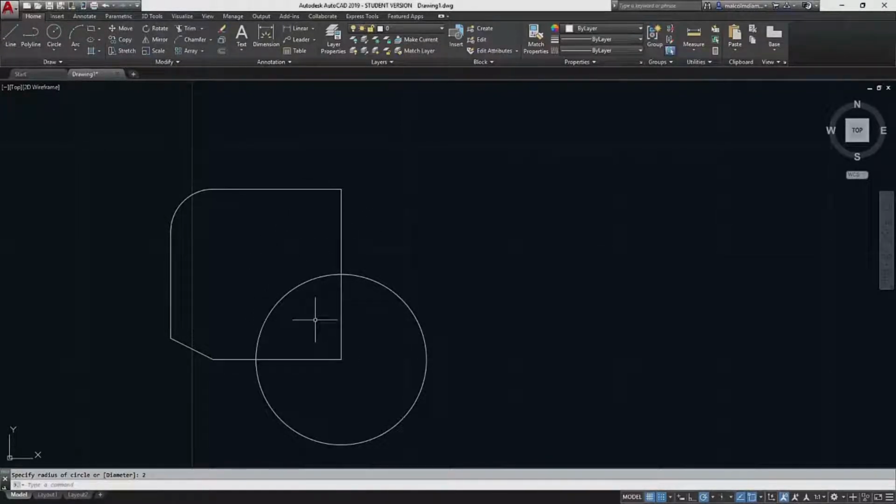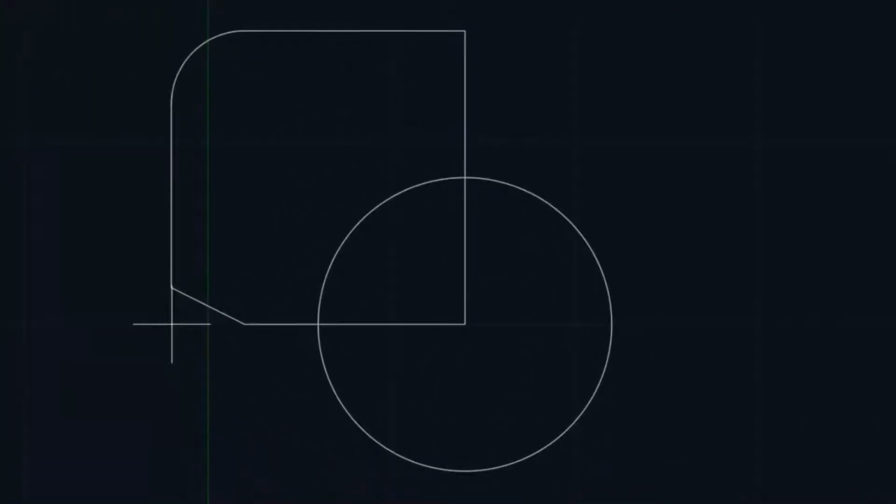What we need to do is now look at putting the 2 other circles on whilst we're in the mood for doing circles. We could go up to the circle command. These circles are 1/2 inch rad, 1 inch across, but looking at the drawing, they could be measured from this bottom point. So I'm going to do the click in type thing. I'm just going to go 1, 2 like that. So these are 1/2 inch segments.